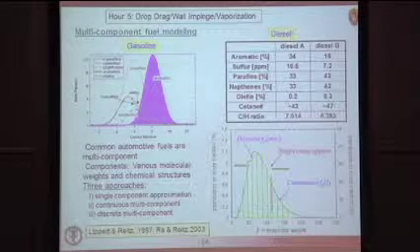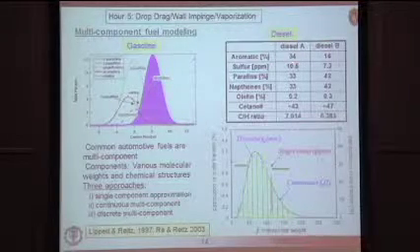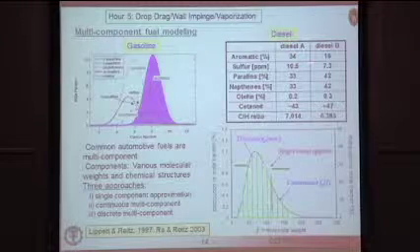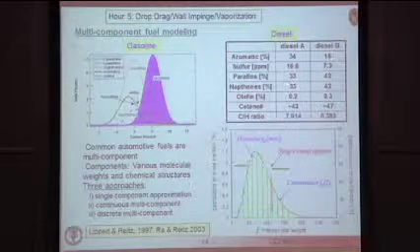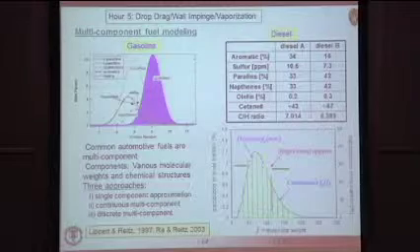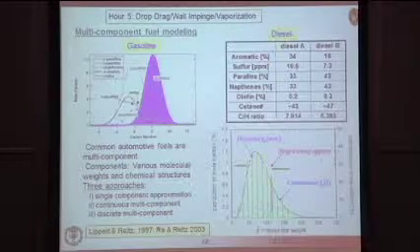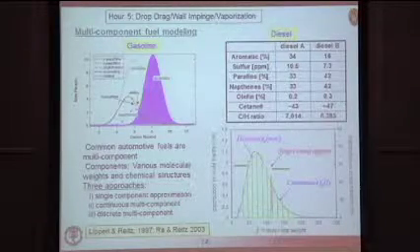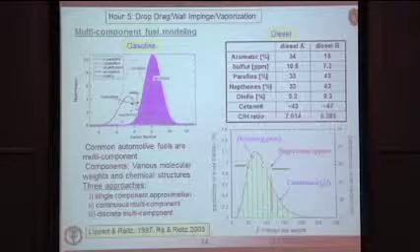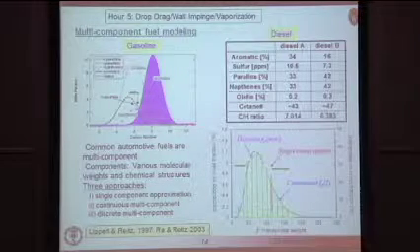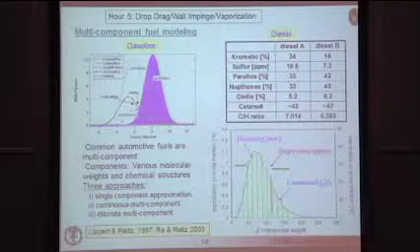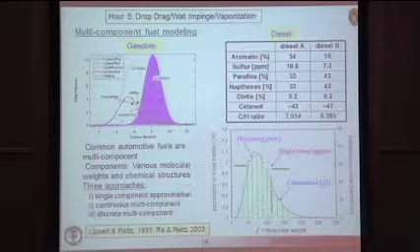And in fact, this list shows for 2 different types of diesels, how much is aromatic, how much of these are naphthenes, paraffins, olefins, and so on. And this has a big effect on how that fuel will perform in an engine. You'll notice that there's a wide range of carbon numbers here, let's say representing the aromatics.